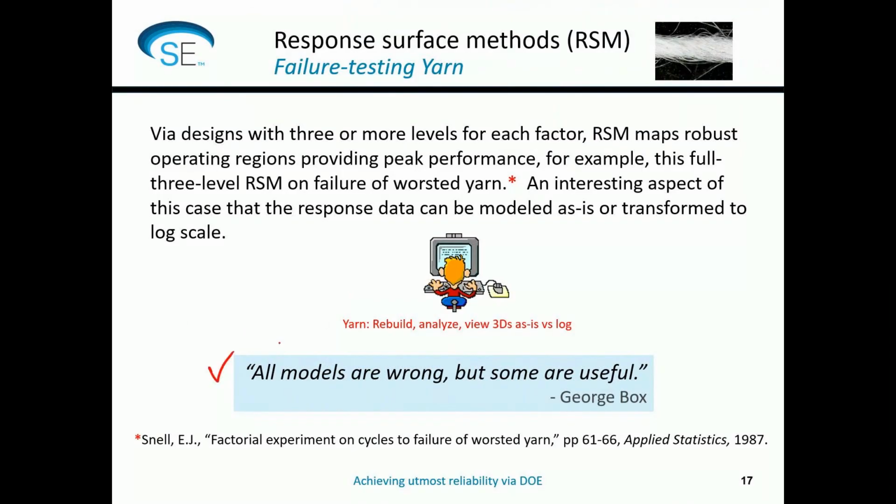And the idea of taking an empirical approach to things, there is nothing wrong with that, provided, of course, that we apply first principles know-how to begin with to try to understand what's going on, and then start doing empirical studies. And so the idea of response surface methods and the standard design that he developed would be basically a core of two-level design with center points, but adding in these additional points on the outside, which are represented by stars, which are called axial points. And this entire design is what Box invented in 1951, along with a fellow named Wilson. And this is called the central composite design.